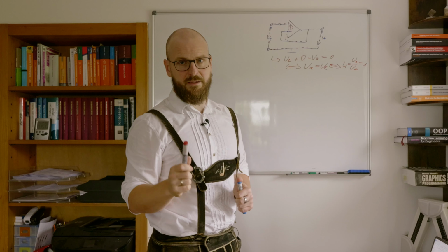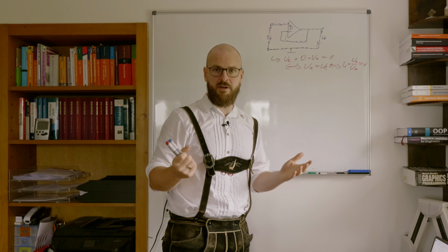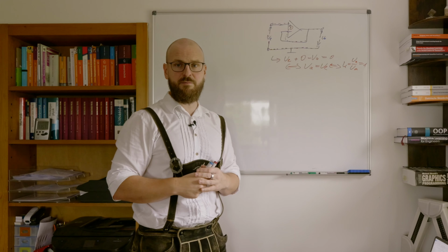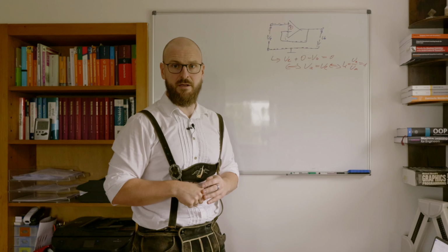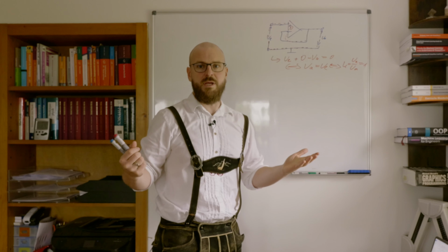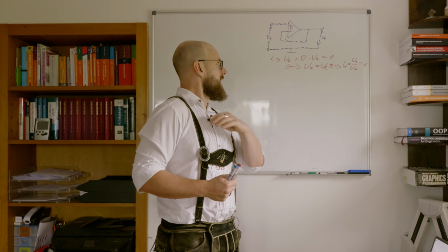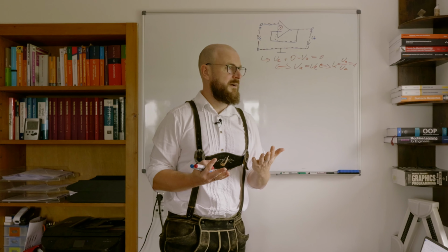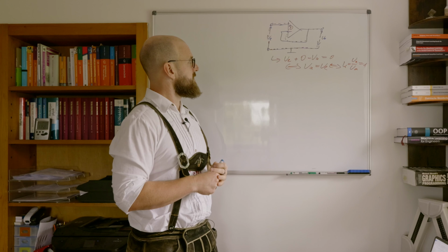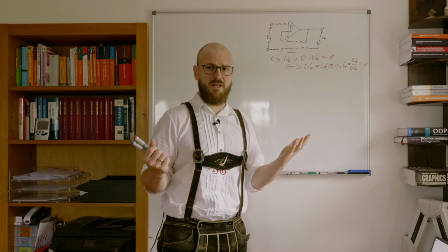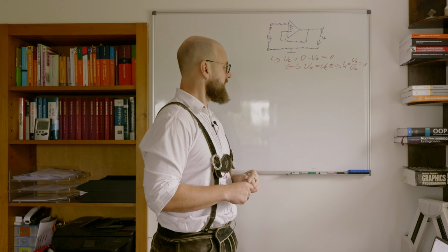We would expect that. Remember the part where we did the general recoupling, the general feedback loop, which told us it's 1 over kg. Now kg is 1, so we get an amplification of 1. The result is quite expected. But now the question arises, why the heck would I do such things and use an operational amplifier having no amplification at all? The answer is quite easy.